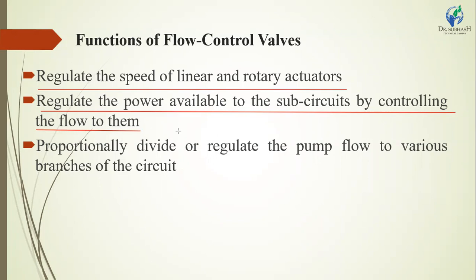In a hydraulic system, only one hydraulic pump and motor set is working, and many more operations have to be supplied from this single hydraulic pump. If you have to regulate the flow to different working parts, an FCV is required in each line, so we can vary the flow control.